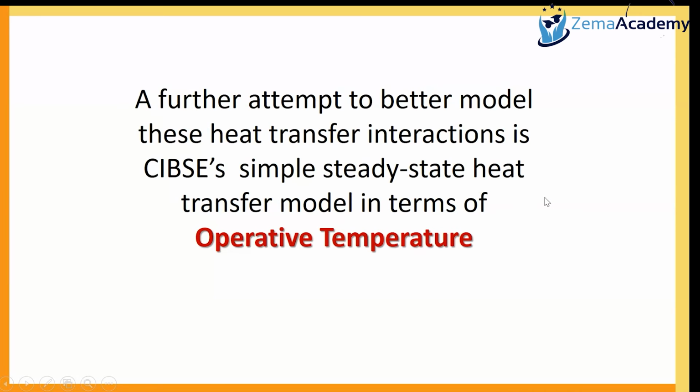So you can see over here that the main difference was the inside environmental temperature. If you look at the definition of inside environmental temperature, it is based on the weighted average of mean surface temperature and inside air temperature. So now it is not only taking into account the convective heat transfer process, but it is also taking into account the radiative heat transfer processes.